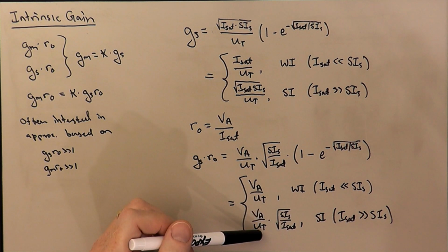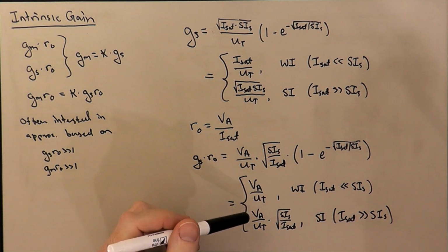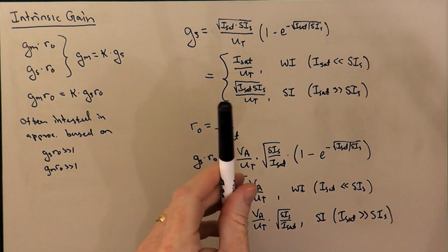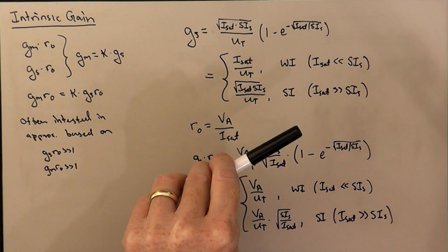And that's primarily a reflection of the fact that the drain characteristic is kind of stretching out this way. VDS sat is getting larger the further above threshold you go. And so the slope deep in the ohmic region for a given current level is getting less and less.